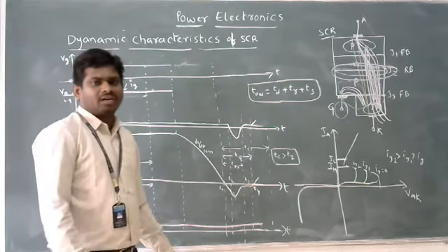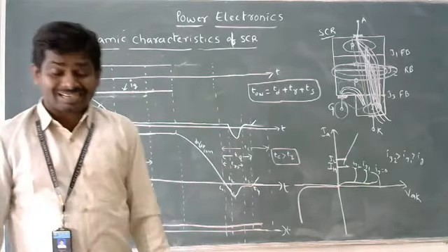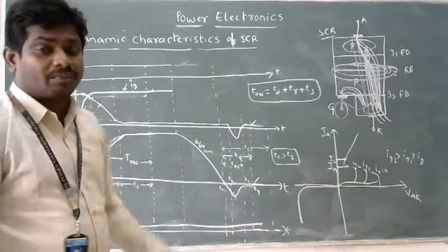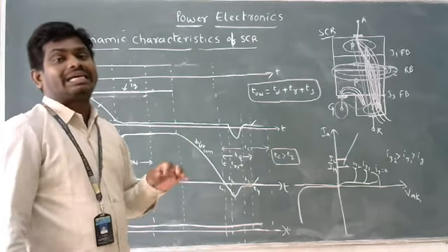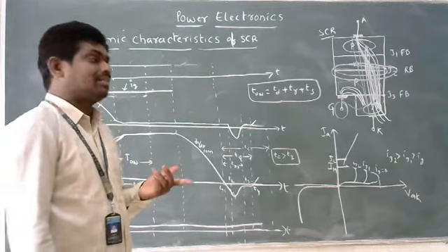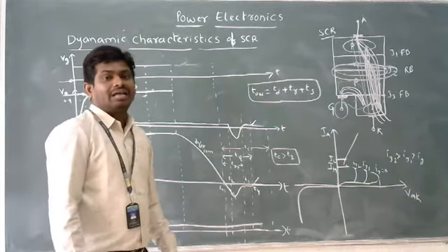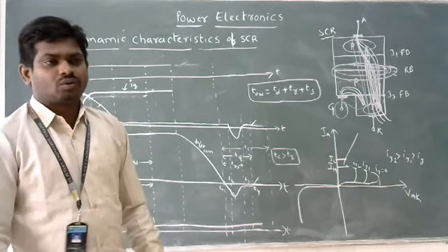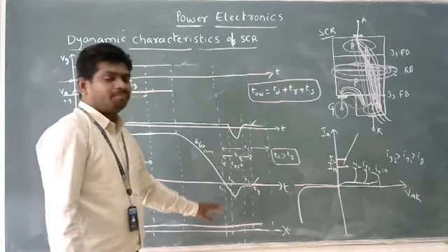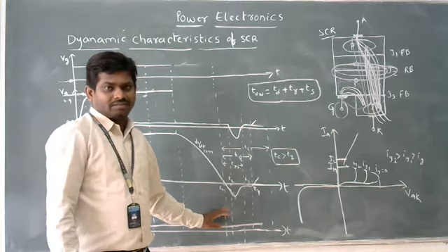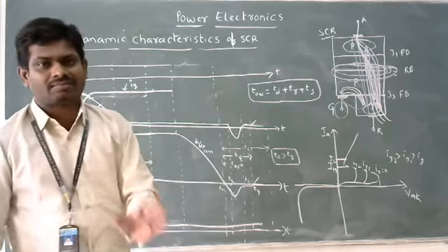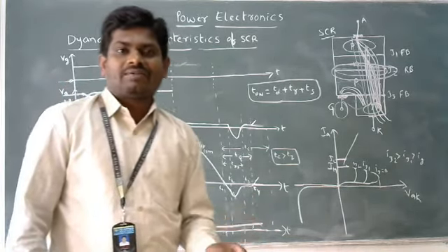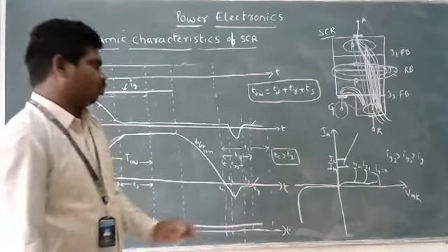After that, to remove the charge carriers at the junction J2, I apply the gate signal in reverse direction. That time is what I call the gate recovery time. So finally, what I am concluding here, the turn-off process is associated with reverse recovery time and gate recovery time. Two factors.